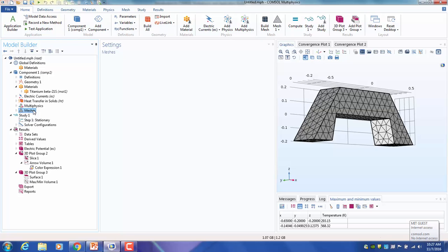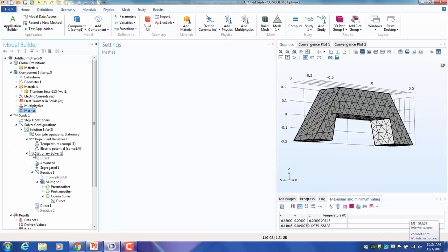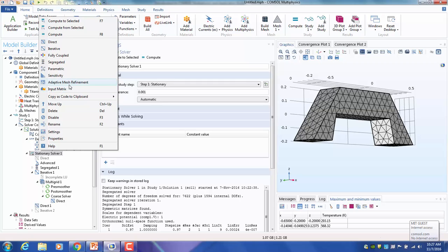There is another approach, a more automatic way under the solver settings, which is to add adaptive mesh refinement. Depending on the error estimate and tolerance you gave, it'll automatically insert mesh points where necessary, say where the gradient is high, where you think a lot of things will be happening. That is more memory intensive, but it's more efficient in determining where to insert the mesh. Otherwise you can do a local refinement manually, which takes more time choosing which region to refine, how fine, and how many iterations. So yeah, something that comes in handy.